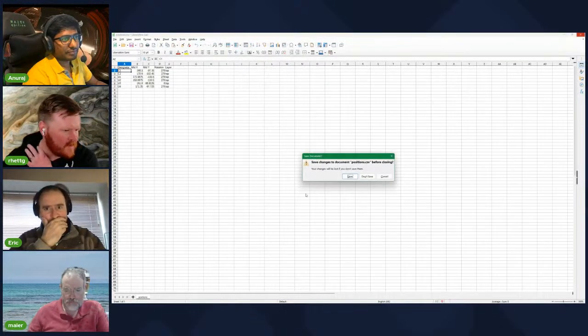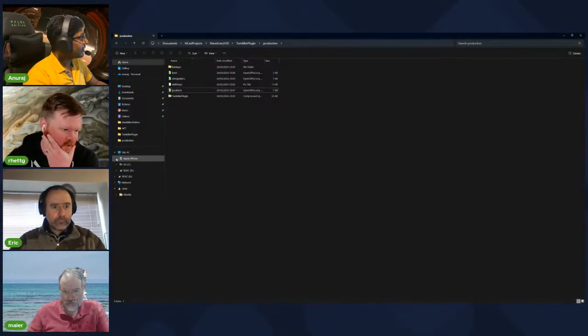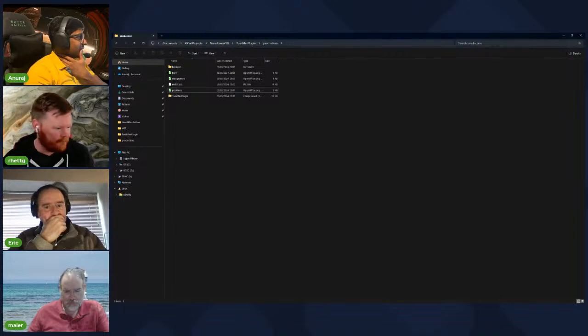It looks like you could have, sorry, I've also got KiCad open. You can select in the properties of your schematic to have it excluded from the bill of materials, or marked as do not place. I think when you import it to JLCPCB, there is an option of do not place on the website itself. You can do it there also.